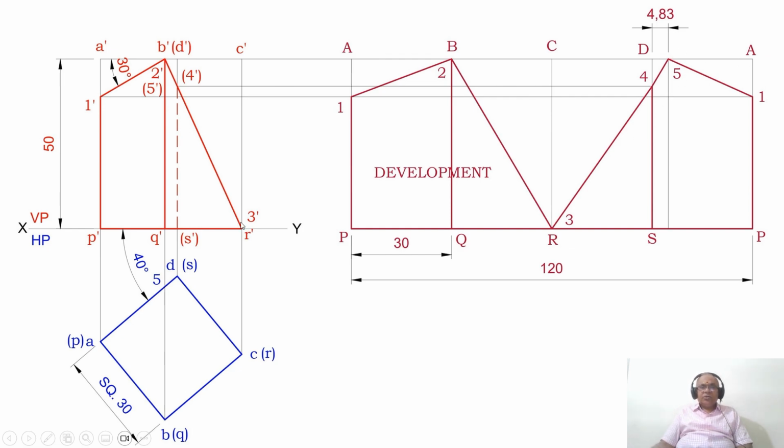So once you do that, what I need to do, at the bottom surface all the edges are dark, therefore from P to P you dark it. So this is how you will be able to transfer the sectional points onto the development and join the completed development like this. So first, join the numbers first. One should do that in the front view, noting which edges are dark. After cutting the section plane, make those edges in the development also as dark lines. And since on the bottom surface you don't have any sectional point passing through, therefore dark this line directly.